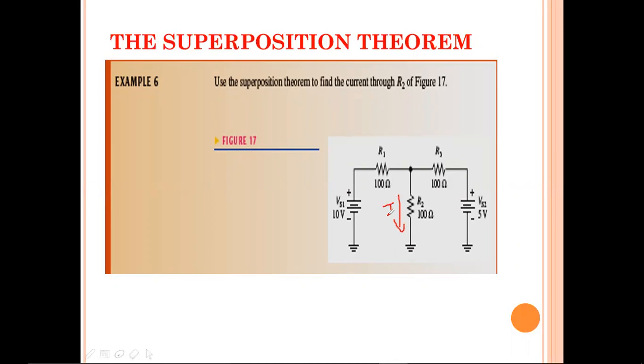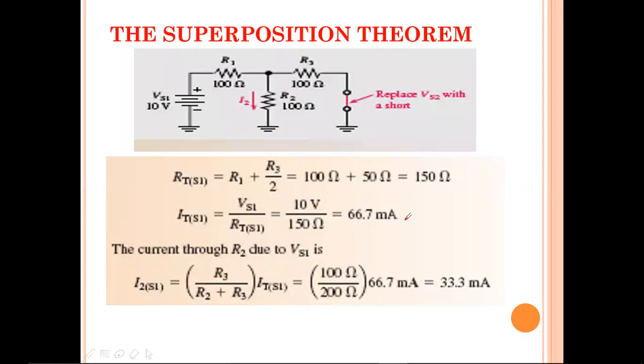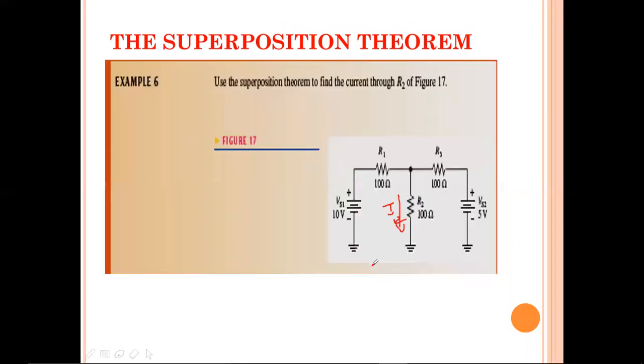As you know, we have multiple steps. I think 6 to 7 steps we have. For that, step 1. What is our step 1? Replace VS2 with the internal resistance, that is 0 ohms. After making it 0 ohms, here there is a resistance. But here the ground is common, right? So to avoid confusion, the circuit is given like this, but this is common for this.